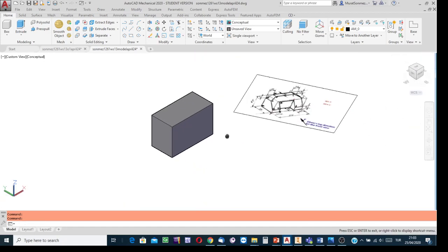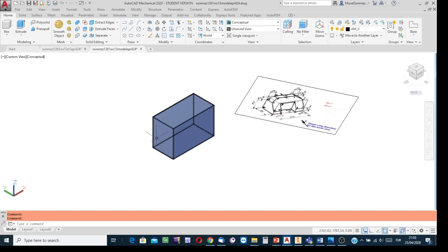Since I'm going to work on this surface, in AutoCAD, unfortunately, the XY plane has to be brought to coincide with that surface. Okay, you know my favorite method to bring the coordinate frame to a suitable place to have the XY plane coincide with the surface on which I need to draw the necessary sketch. I use this tool, the 3-point tool.